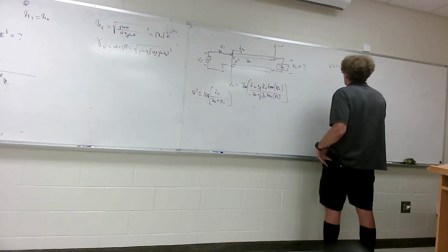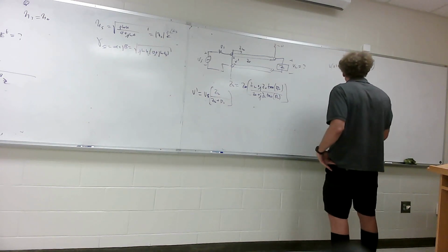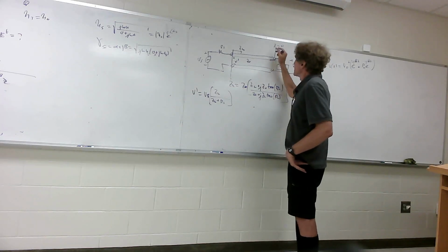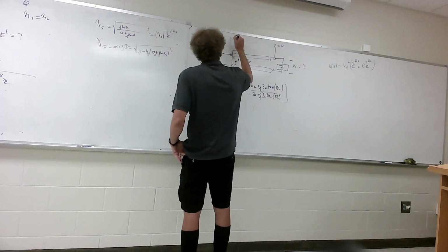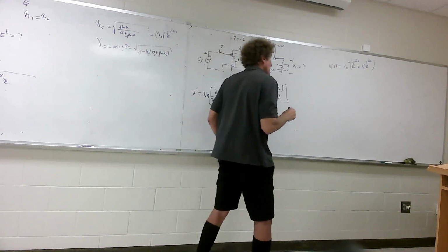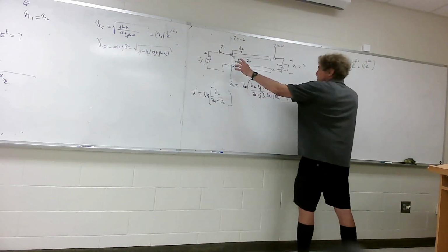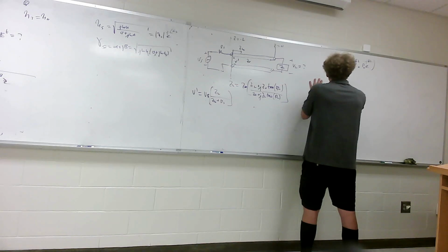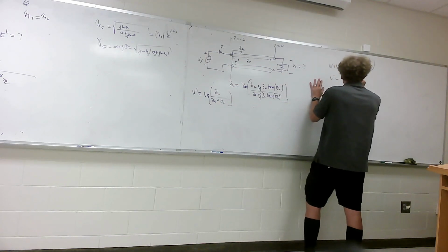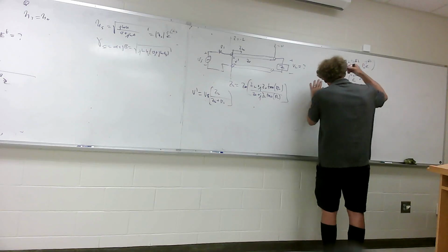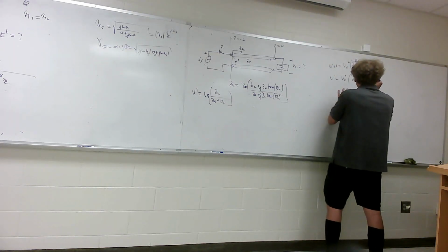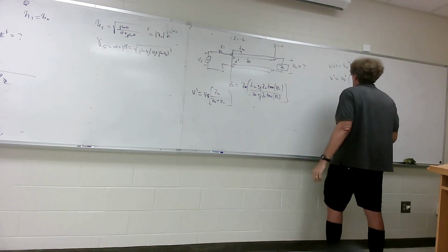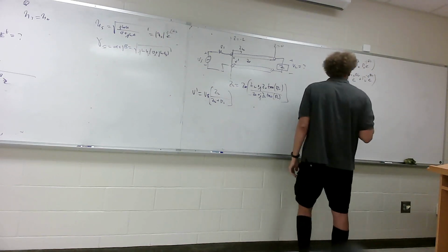And what you ended up doing is saying that if this is 0, then this point right here would be z is minus L. So you get V of z at minus L is V prime, you get V prime is equal to V0 plus times e to the plus j beta L, because z is now minus L, plus the reflection coefficient of the load times e to the minus j beta L. And we've got V prime, you could solve for V plus.